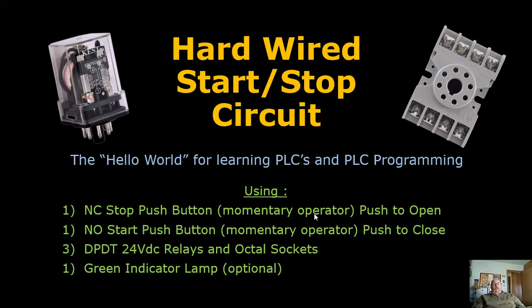with a momentary operator, which means that when the operator pushes the button, it will open the switch. When the switch is in its rest position, or its normal position, it will be closed. We're going to use one normally open start push button, again with a momentary operator, so that when the operator pushes that push button, the switch contact will close.